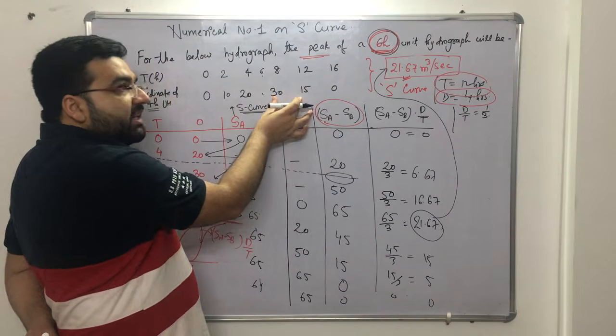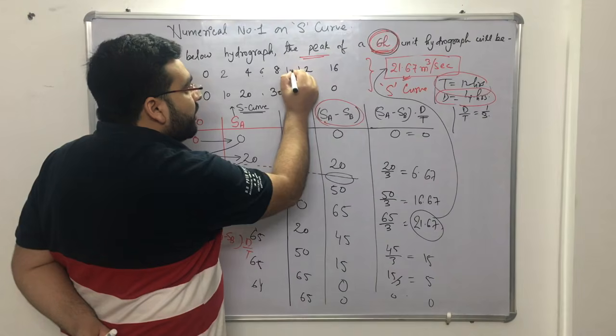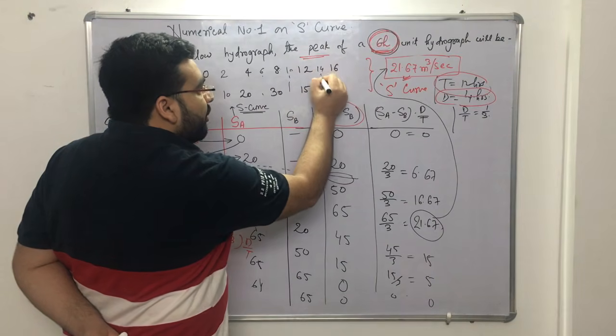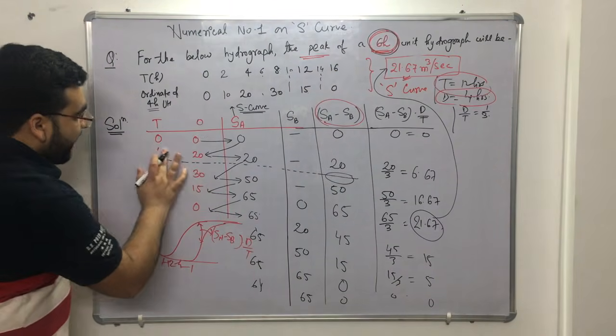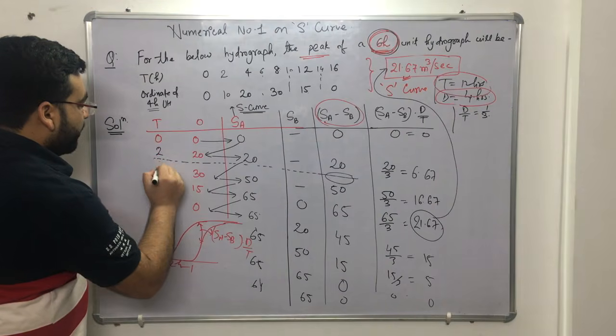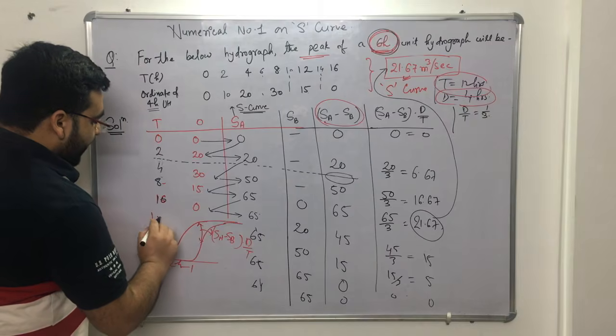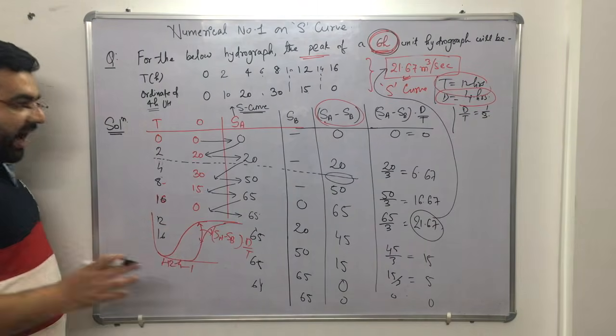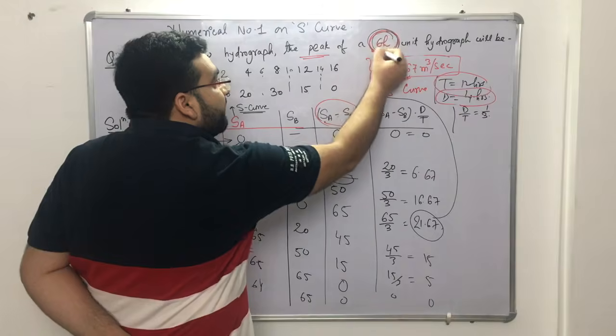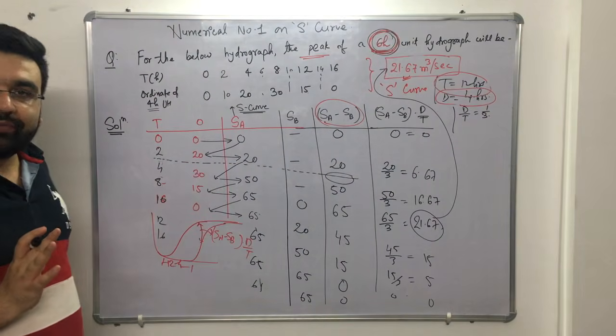I get the incremental value and I get the value at 10 also. And similarly 14 also, right? So this table I will draw for 0, 2, 4, 8, 10, 12, 16 and so on. And that is how I can shift it with a 6-hour duration.